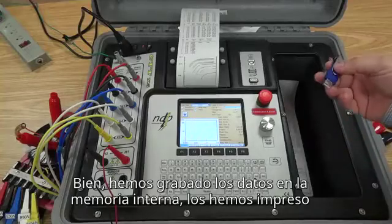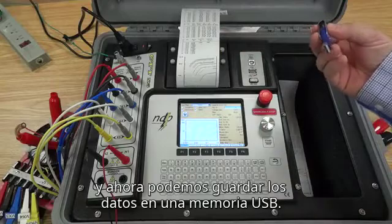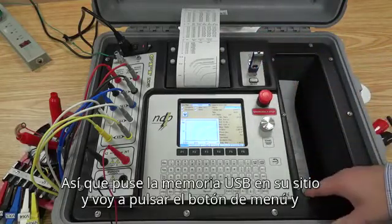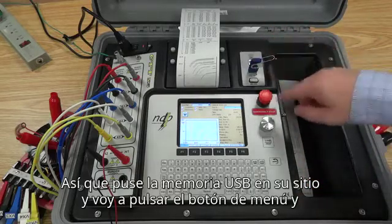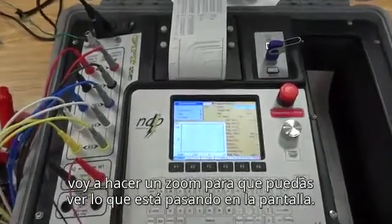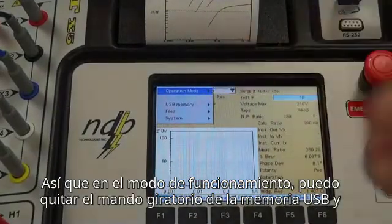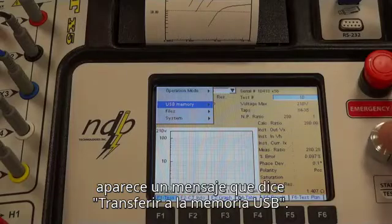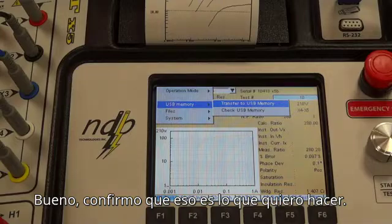Alright, so we've recorded the data into internal memory, we've printed it out. Now we can save the data to a USB thumb drive. And so I put the USB thumb drive in its port, and I'm going to press the menu button. And I'm going to zoom in so you can see what's happening on the display. So operation mode, then I can move the rotary knob to USB memory, and there pops up a message saying transfer to USB memory.